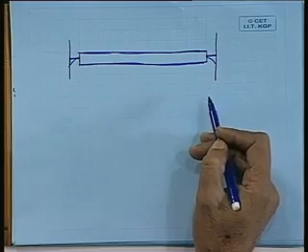You see, if you have to change the entire bulkhead, you have to cut it open, bring it into pieces, take it out from whatever opening is available, and then how are you going to take it in? You have to take it piece by piece, assemble it there and put it in position. Or otherwise, you cut open the deck, take out this damaged part, prepare the thing in the hull shop, bring it into position and put the deck back once again. Hell of a job.